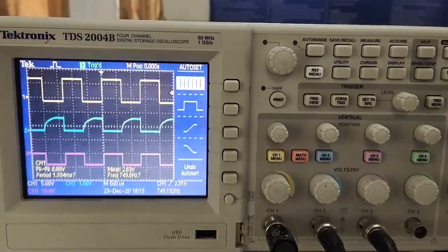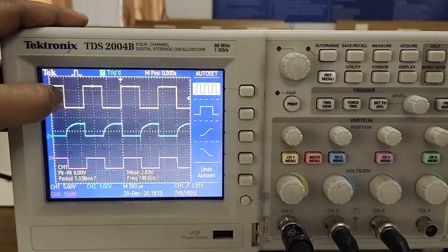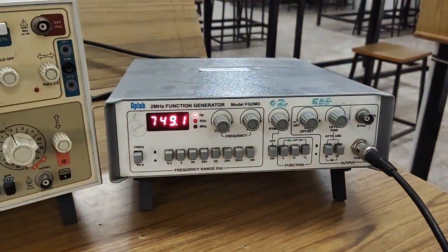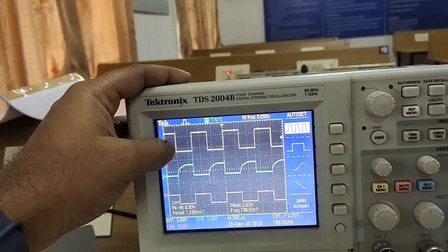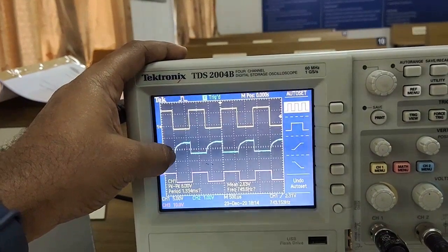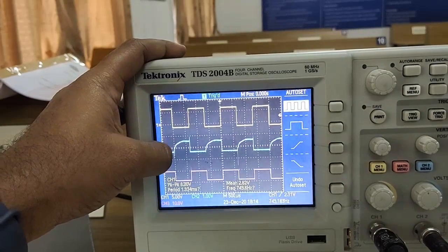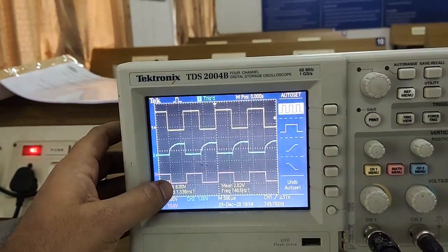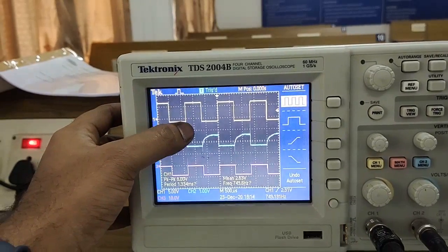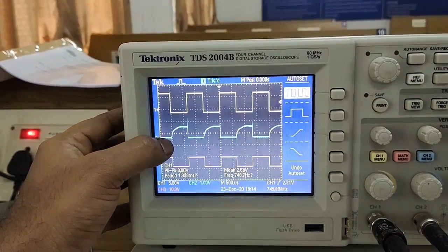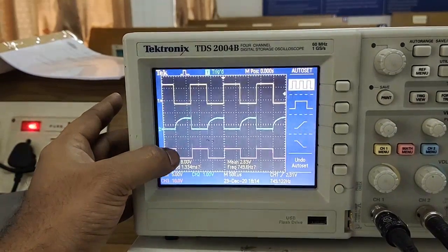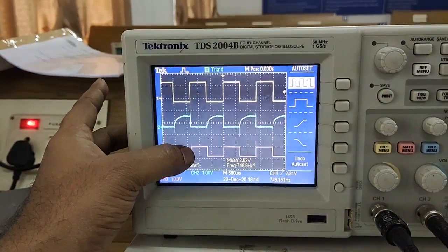So here we have to measure the first input voltage and its frequency. It is already given here in your function generator, so you can easily measure the frequency, and this is the voltage across your capacitor. So you can see that for each trigger we are giving, for the negative going trigger, the output remains in stable state and enters into the quasi stable state like this, and again gets back to the stable state.